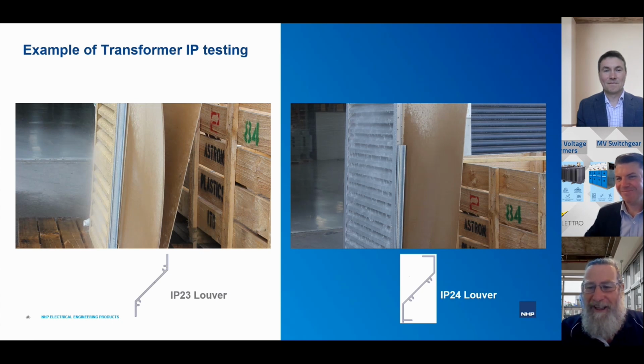Get to Frankfurt, get an email to say, unfortunately, the transformer in the kiosk now had exceeded the standard as far as its top oil rise. So in solving one problem, reducing the ingress of water into the oil containment, we created another, because the louvers were no longer effective at getting the heat away from the transformer installed inside.